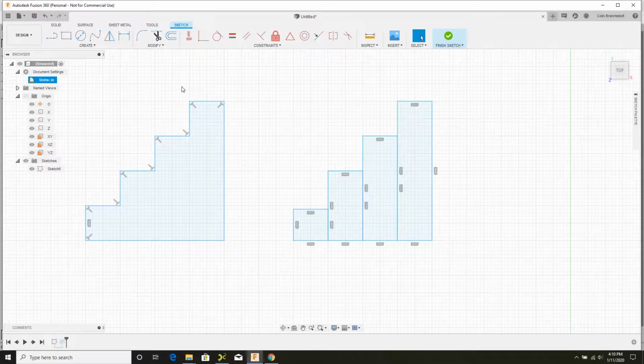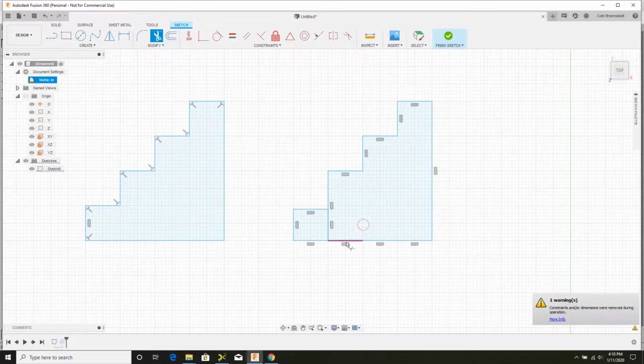So they have tools here for that. They have something called a trim tool, right? So trim is kind of like our eraser. It's a little bit smarter. It doesn't make us go up and down. It thinks, oh, there's a line here. Well, it probably wants us to trim it, so we can trim that line. Now, remember how there were two lines? Because there was a line here, and then this one went over there. You got to hit trim twice. So that's trimming one side of the box, that's trimming the other side of the box. One side of the box, other side of the box.